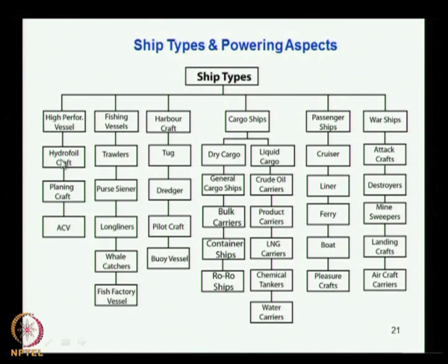So the hydrofoil craft moves at a higher speed, usually a small craft, and due to the hydrodynamic effect there will be a hydrodynamic lift that pushes it up partly above water compared to the displacement condition, which reduces the resistance. So here what you have to do is find out the actual displacement of the vessel in the displacement condition, and what is the underwater or submerged portion when it is in the planing condition, which enables you to find out the resistance of the vessel. I am sorry, I was just explaining this planing craft.